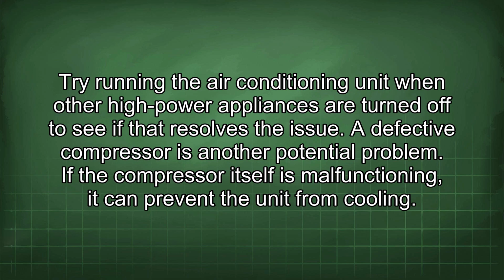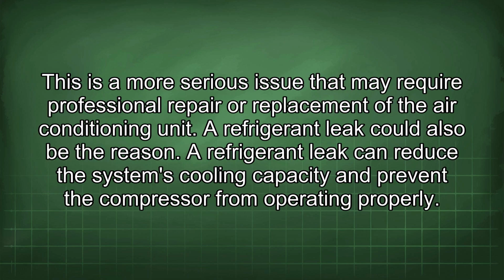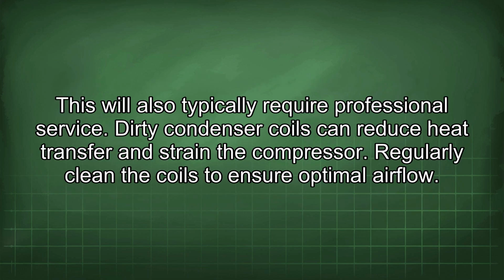If the compressor itself is malfunctioning, it can prevent the unit from cooling. This is a more serious issue that may require professional repair or replacement of the air conditioning unit. A refrigerant leak could also be the reason. A refrigerant leak can reduce the system's cooling capacity and prevent the compressor from operating properly. This will also typically require professional service.